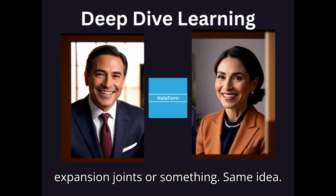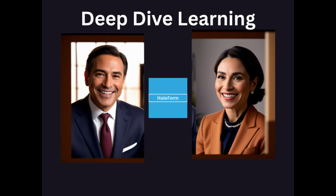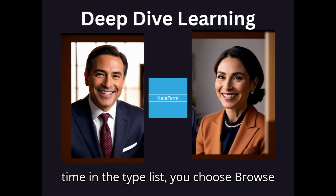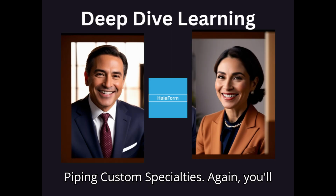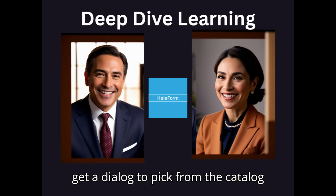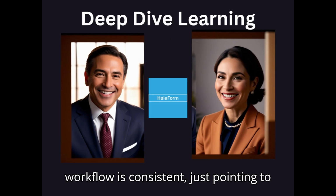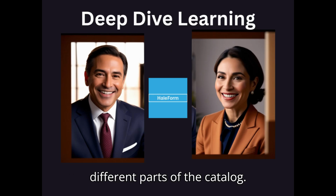Specialties, like expansion joints or something. Same idea. You select your insertion point, but this time in the type list, you choose Browse Piping Custom Specialties. Again, you'll get a dialog to pick from the catalog, More, or recently used items. So the workflow is consistent, just pointing to different parts of the catalog.